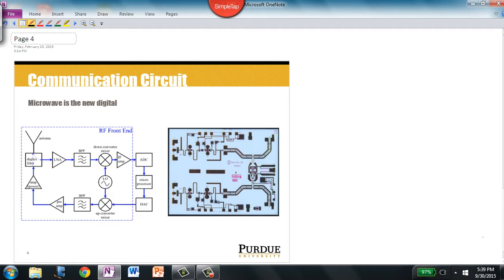The vast majority of modern microwave engineering is really going to be in the signals and communications field. So these are largely communication devices: Wi-Fi networks, Bluetooth networks, satellite networks, cell phone networks, things like that. For example, modern clock speeds of microprocessors are usually around 4 gigahertz. The GSM cell phones operate at 1.85 to 1.9 gigahertz uplink and 1.93 to 1.99 gigahertz downlink. Wireless LAN uses spectrum in the 2.4 gigahertz and 5 gigahertz bands.